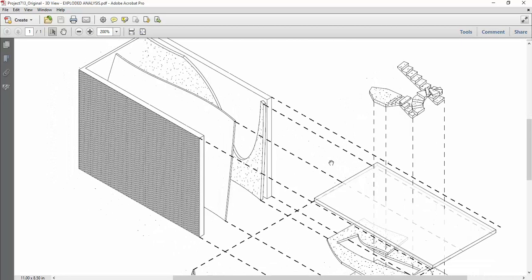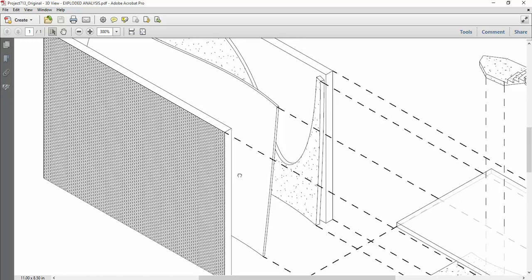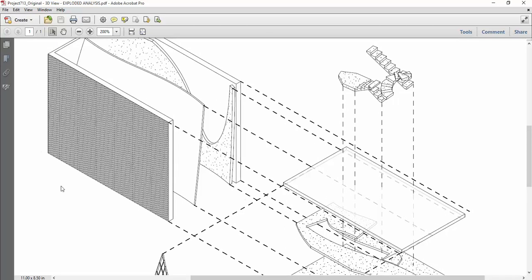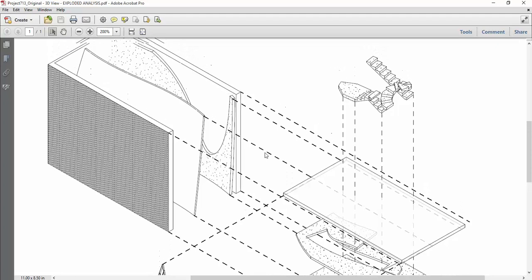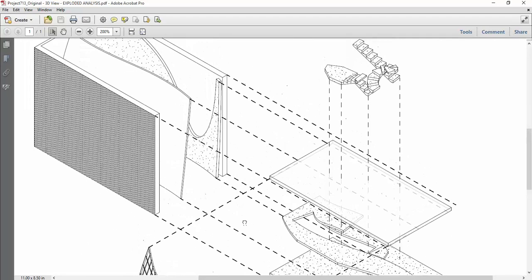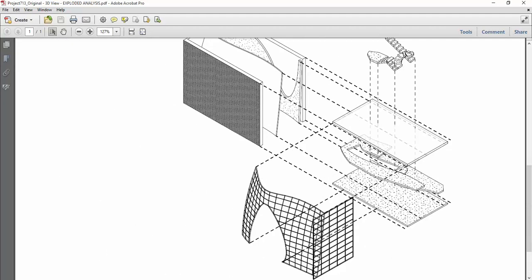And now that you zoom in, you can already see that I have plugged it here, a brick wall. If you want to change the brick wall, as you guys have seen in previous tutorials, you can always go under the edit type of the wall, or you can override this texture only for this view from the visibility and graphics menu, because the exploded analysis doesn't really have quality of materiality and realism. Just the parts, you may end up really overriding from the visibility and graphics menu all of those textures and keeping them simple and white. Great, so we'll close that.